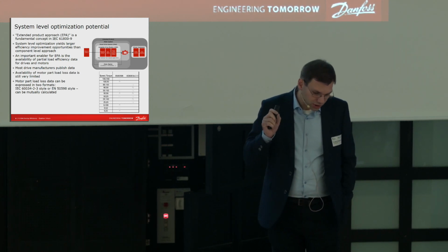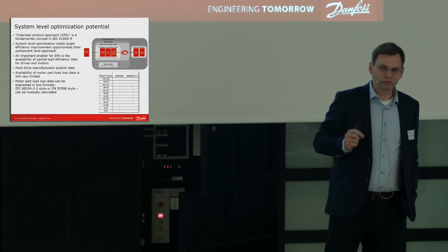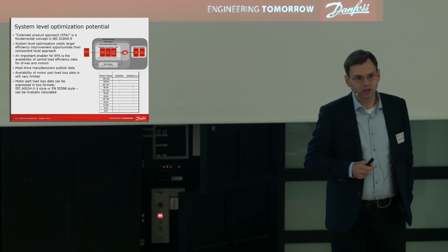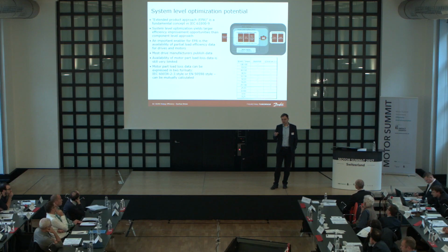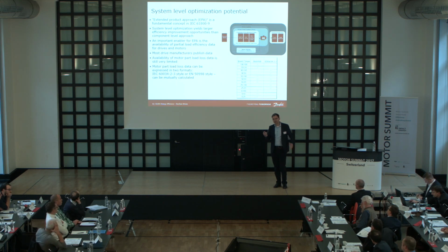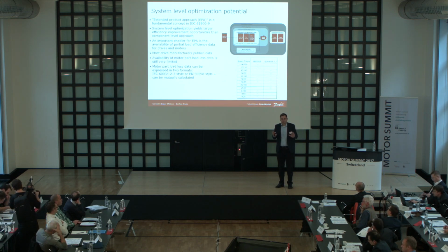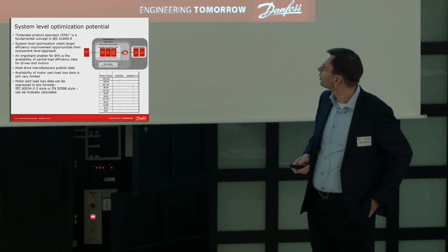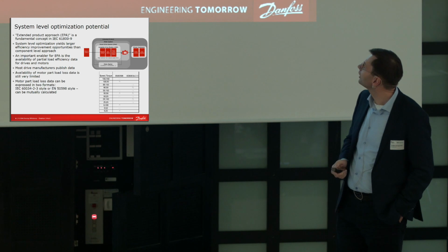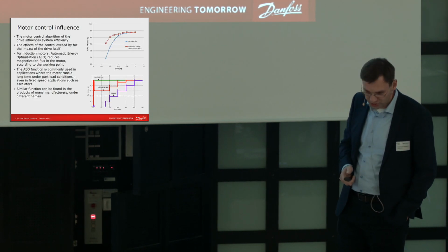And then there is also the issue about in which format we should present the data. You can use the format from EN 50598 with 8 part load points, or you can use the format with 7 part load points from the IEC 60034 motor standard. So there are two formats. They are mutually interchangeable, and our experience shows that the IEC standard gives better results, but we need the data, no matter in what format. So that's an important enabler for system-level optimization.